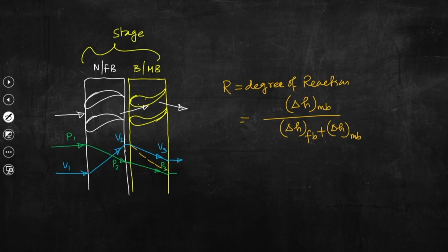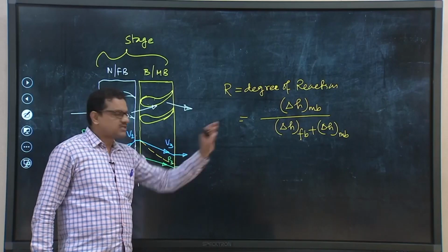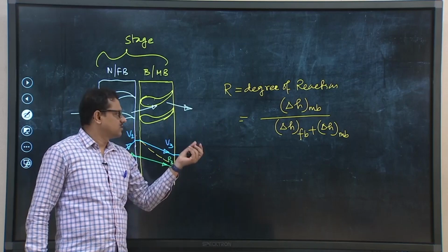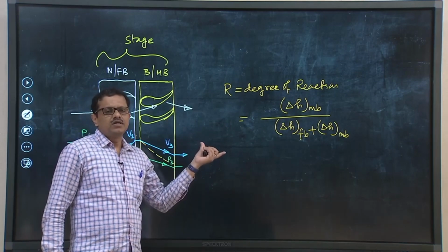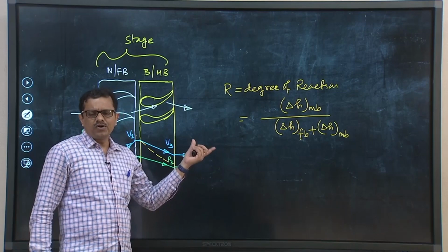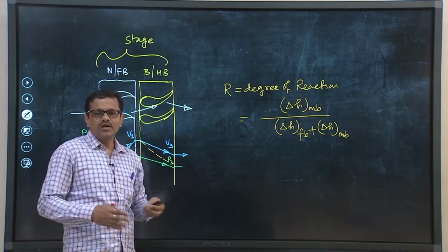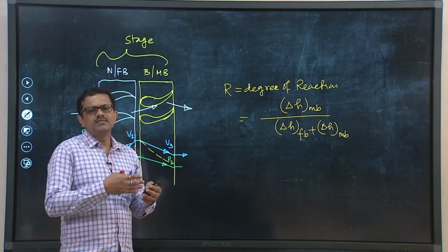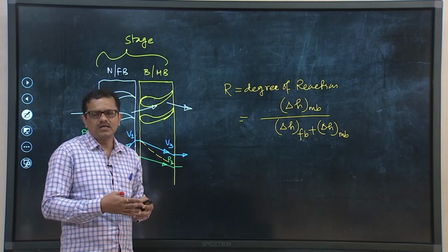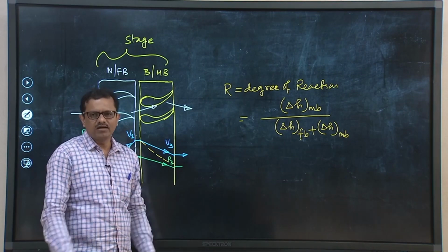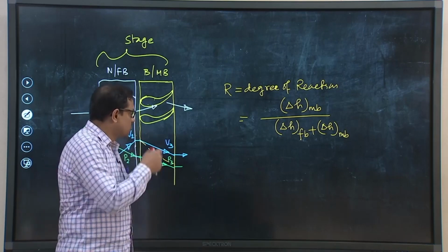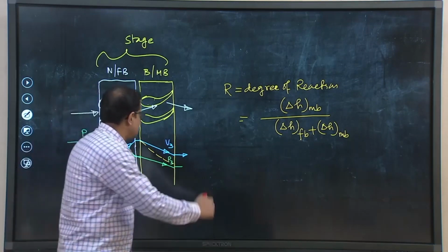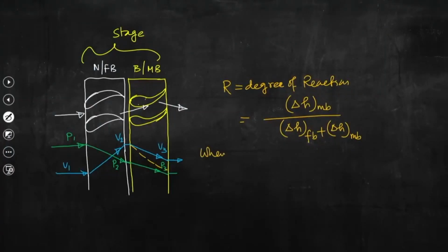So today we shall analyze the reaction turbine, of course, by drawing the velocity triangles, only to establish the mathematical form of the blading work or diagram work, or the diagram efficiency or blading efficiency. So, we will consider a particular case when R equal to half, that is, a 50% reaction turbine.